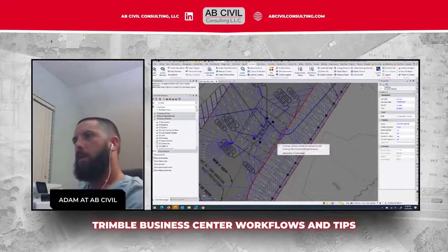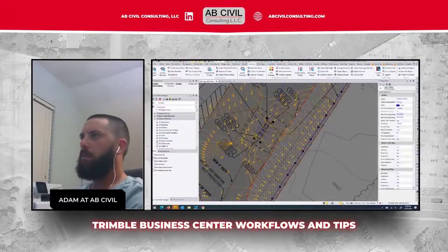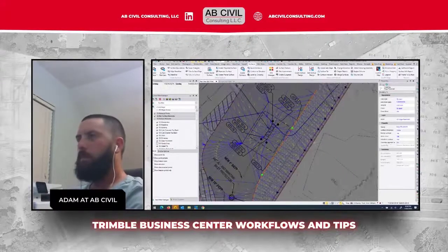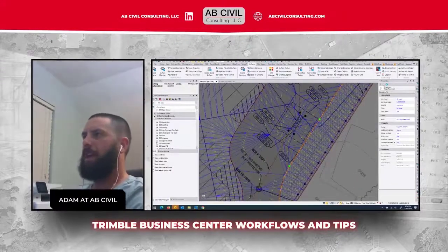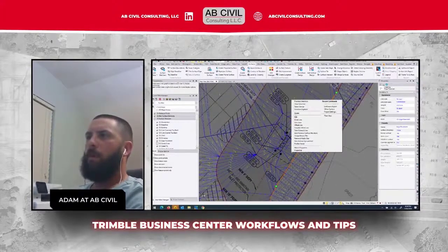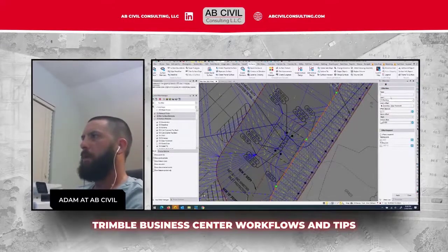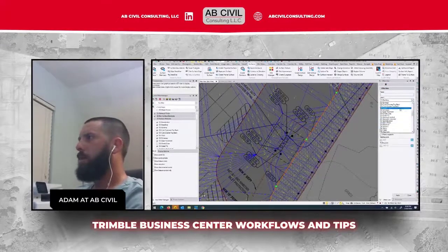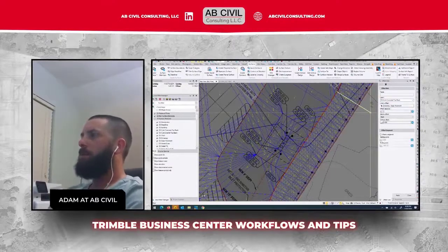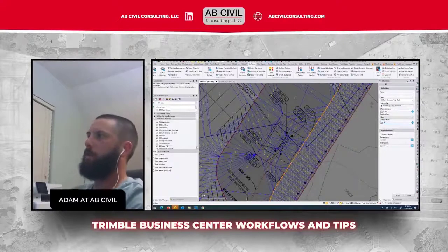I'll go right here. So if I was supposed to have a sidewalk, I'm going to first select this edge of pavement layer, and I'll add it as curb, and then I'll add a sidewalk. So I'm going to right click, offset line. It's a really simple command. Just going to pick curb top back. So I'm going to offset at 0.5, tab over to the right, vertical 0.5.